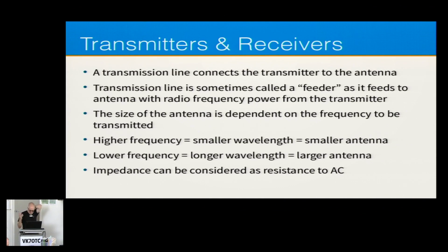Okay, so this is connecting your transmitter to your antenna, sometimes called a feeder because it feeds the antenna. The concept you need to know is the size of your antenna depends on the frequency to which you're transmitting, and it's an inverse relationship. So at higher frequencies there are smaller antennas. At lower frequencies, longer, larger antennas.